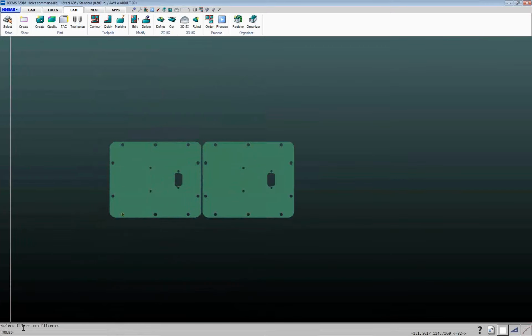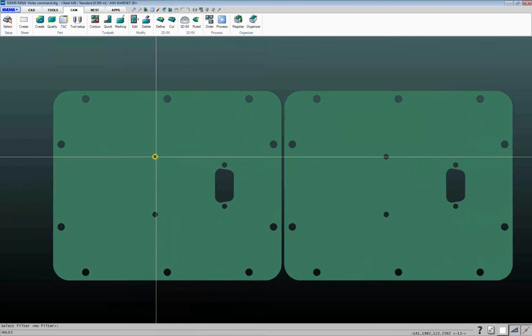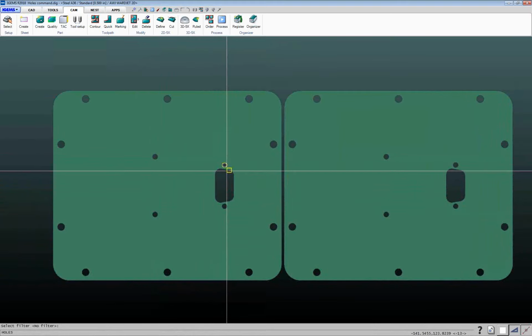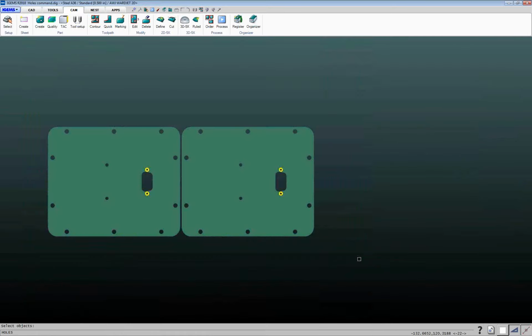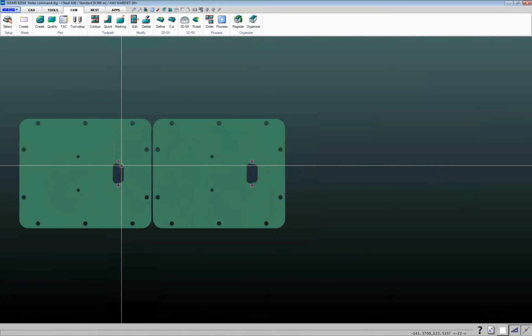After you start the command, down here at the bottom it says select filter. Basically if there was just a certain size hole that you wanted to drill rather than drill and cut or cut, you can say, all right, I want to drill holes of that size. And now it's prompting me to select objects. So if I go around and click both these parts, it's going to find holes of that same size, and then it's going to add the drilling command to those holes.